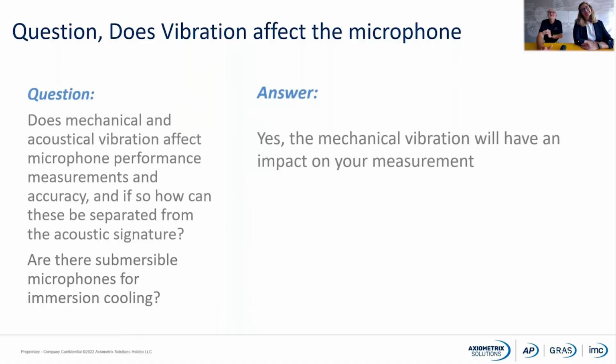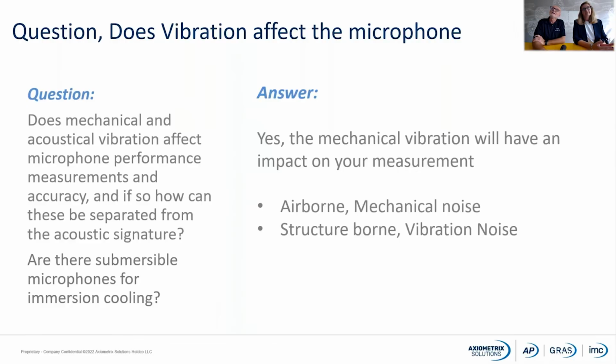Yes, mechanical vibration will have an impact on your measurement. It could be airborne noise, or it could be structure-borne, where it is a vibration noise. With airborne noise, I mean that your microphone is mounted somewhere, and next to that you have something which is vibrating a lot.